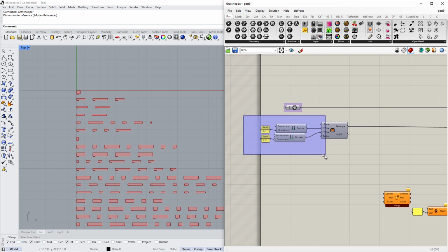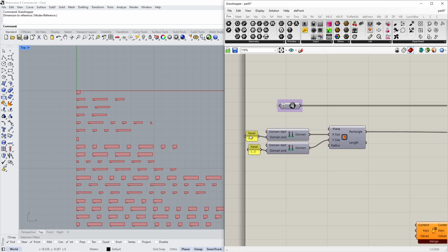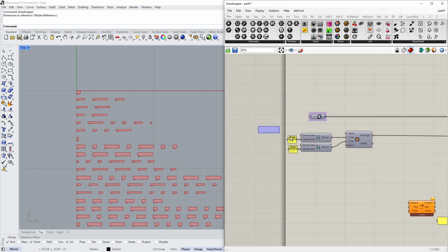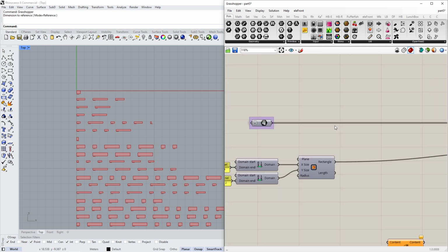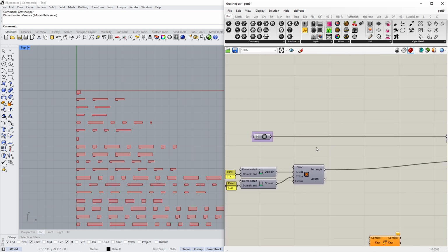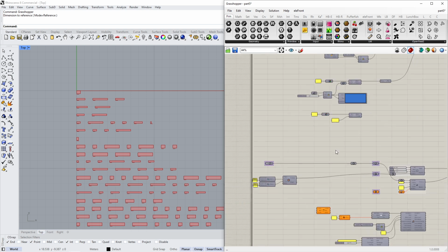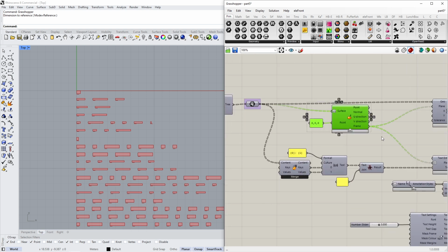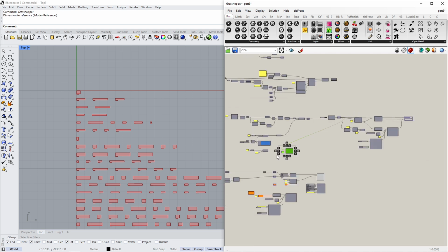Because before I insert the geometry, I forgot, we're going to lay them all flat on the XY plane. It's not necessary per se, but it's just for us to have a bit more clear how the geometry is going to look like. And also we can more precisely specify a base point. So the way to do that is using the evaluate surface component, this one. So we get the frames again.